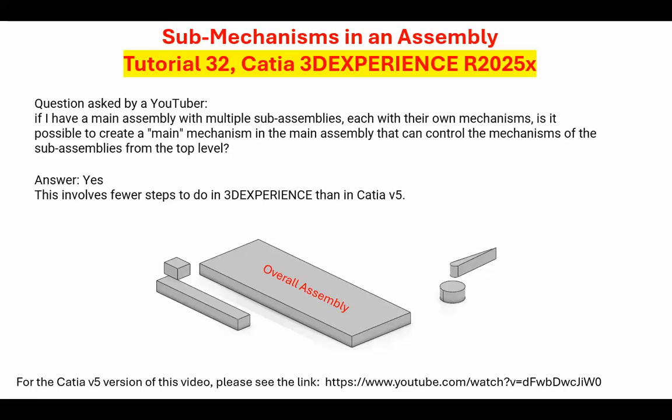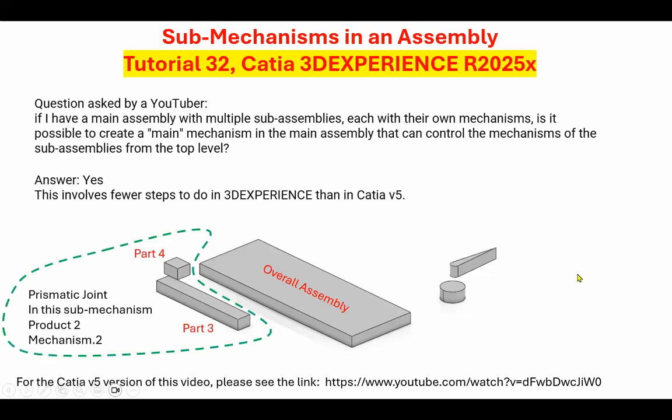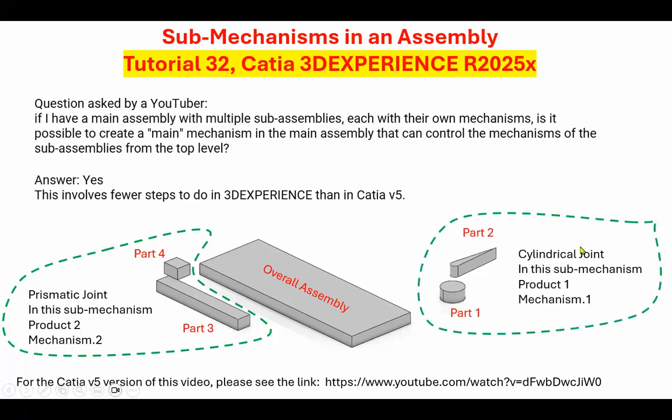I have two sub-assemblies. One of them has its own mechanism and it's made out of a prismatic joint like this. So this product 2, which is my first sub-assembly, is going to have these two pieces in it, and it's a prismatic joint, so there is a mechanism in it. And the other one, product 1, is going to have its own mechanism, and it's a cylindrical joint between these two parts. Later on, I'm going to bring these things and show you as an example to what the YouTuber is asking, how to put them together in this overall assembly.